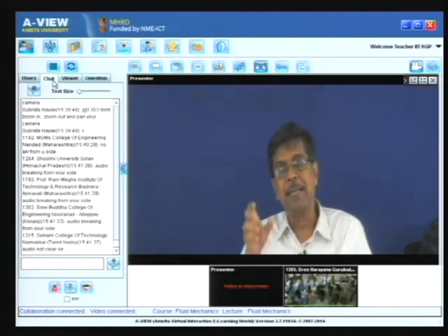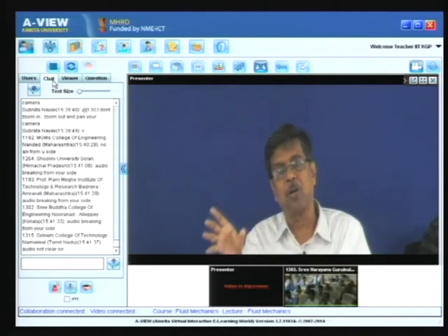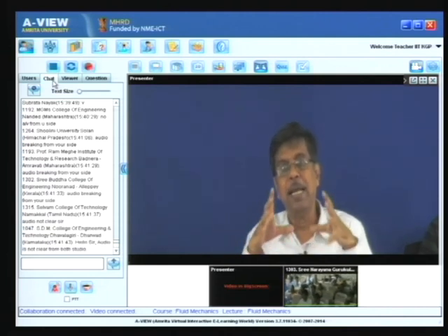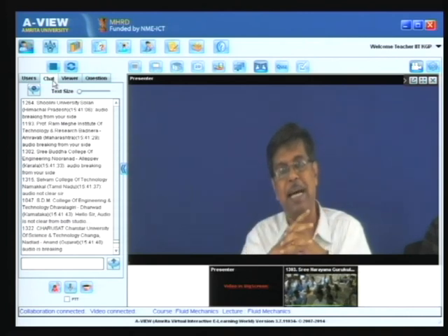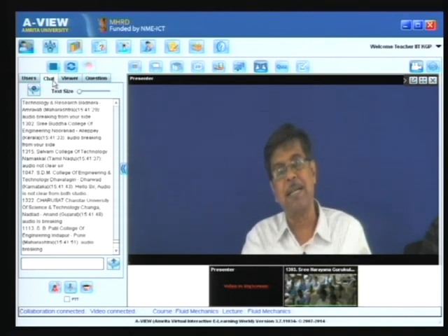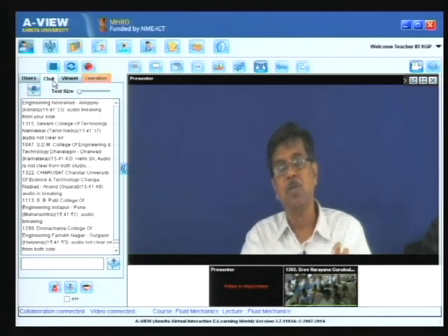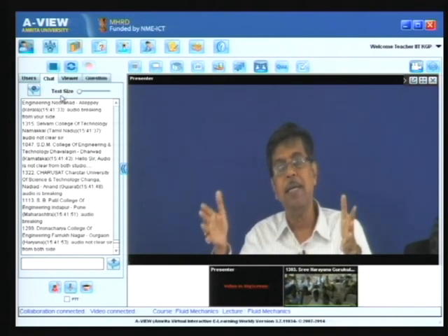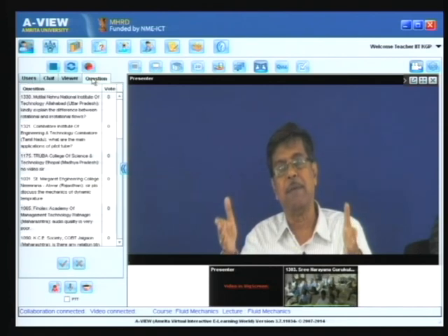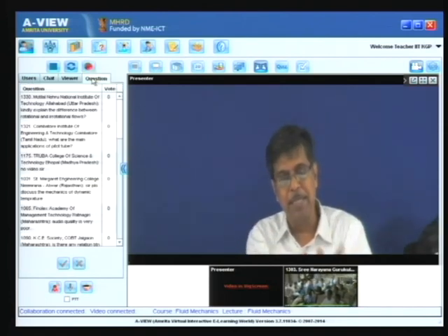But the right hand side quantities are for a control volume, and since in the limit delta t tends to 0 the control volume and system coincide, the force exerted on a system means exerted on the control volume. Therefore, the entire statement of conservation of momentum is valid for the control volume, which is known as the momentum theorem. There is no system in the example.